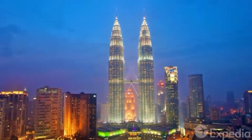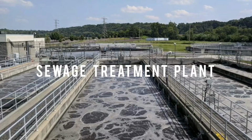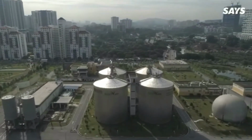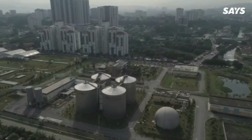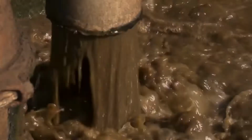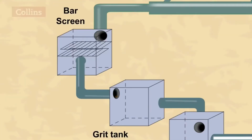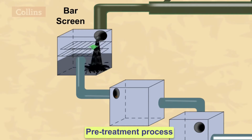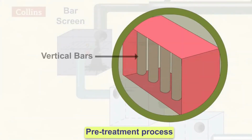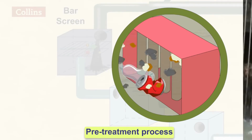One of the most common forms of pollution control in Malaysia is wastewater treatment. A wastewater treatment plant is a facility in which a combination of various processes including physical, chemical, and biological are used to treat industrial wastewater and remove pollutants. The first process involved at wastewater treatment plant is pre-treatment process. The pre-treatment process involves the sewage being sent through bar screen to remove large floating objects like metal can, paper, and plastic materials.